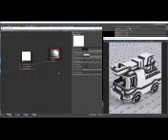This is a simple procedural black and white map, and you can think of it as any other black and white map. For example, if I connect this map to the reflection color input of my Corona material, the black parts are gonna make the material to not reflect at all, and the white parts make it completely reflective. So let's disconnect the ambient occlusion for now.